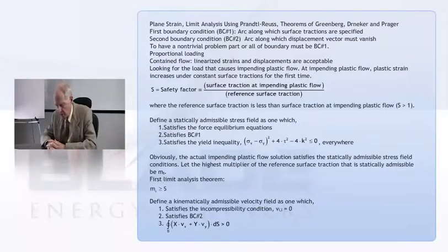Okay, now they have an awkward way, in my way of thinking, for defining things. But you have some reference loads, and if you have a pressure on something, and that's the only load, make it 1 psi. What have you got to lose? Put it in there, and that'll be your reference load.